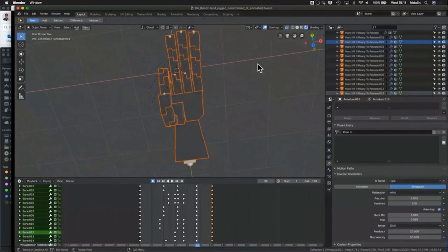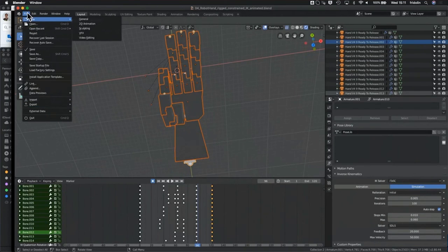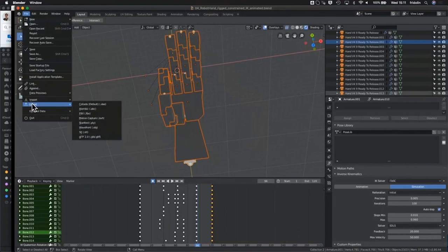A final thing, so we've made it do some cool things within Blender, but we're talking about augmented reality here, so we want to get it into Unity to then compile into an app, for example. Now, to do that, there is a format that I find to be particularly nice for moving complex things between softwares, and that's the FBX format. So if we selected everything, and we went down to File in the top left of the whole window, not just your 3D viewport, and we go to Export and FBX.